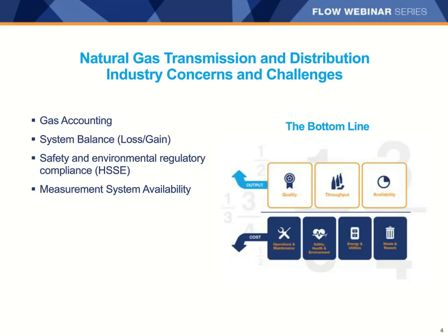Most rotary meters today deal with this potential safety issue by building in an emergency bypass around the metering chamber that will open whenever the meter mechanical component seizes because of particle contamination in the flow stream, but this allows the gas to pass by unmetered.